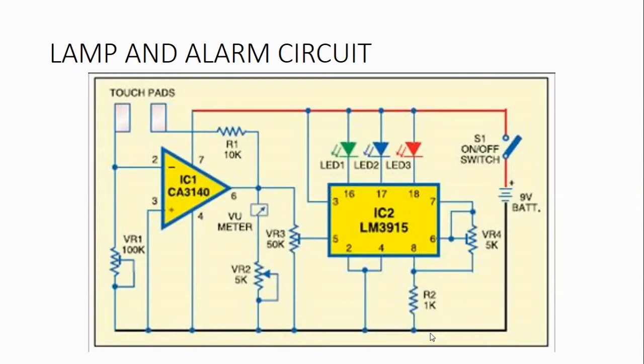The test case includes a completely enclosed testing area and a dedicated personnel safety interlock system that monitors a single interlock access door and controls the application of high voltage, to provide personnel protection against high voltage safety hazards inside the chamber.